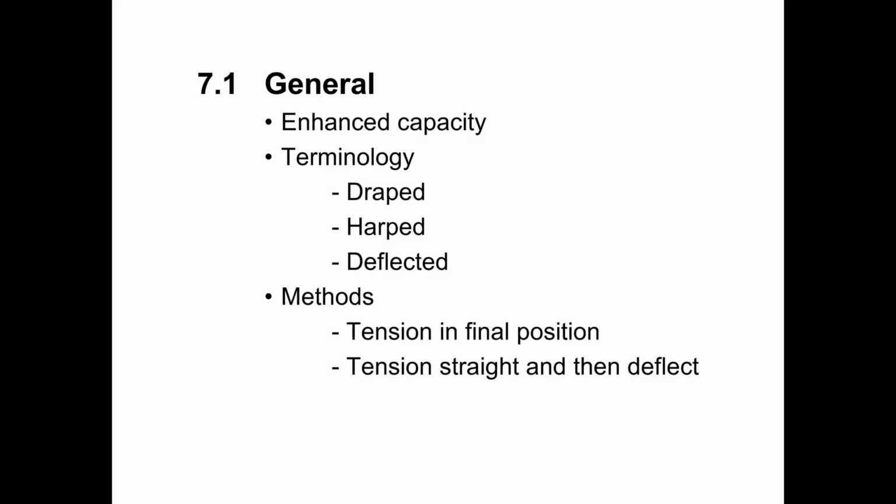However, the disadvantage to tensioning in the deflected shape is that we get friction that builds up at each location where the strand is held up or it's held down. And so for a long bed, the accumulating friction along the length of the bed may make it difficult for us to tension the strands in the deflected position and get them in within tolerance requirements. Okay, so that's the downside to tensioning in the deflected position.